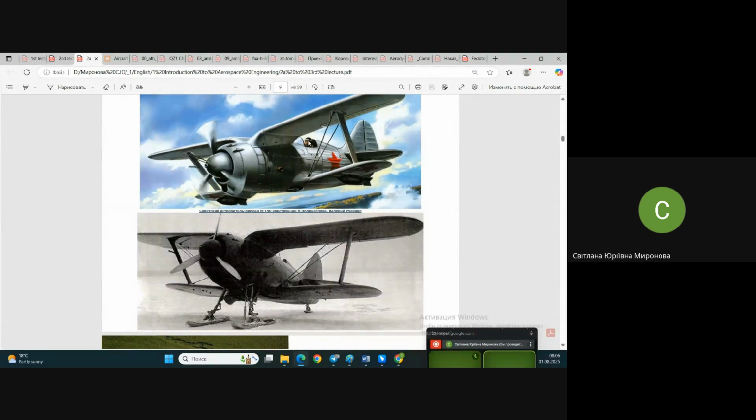Pay attention to where the pilot is, the cockpit is here, and in order to provide visibility for the pilot, the ability to see something in flight, they were forced to use the gull wing. One more possible decision, of course, is to place the wing even lower to this side. Why did they break the wing in this place?